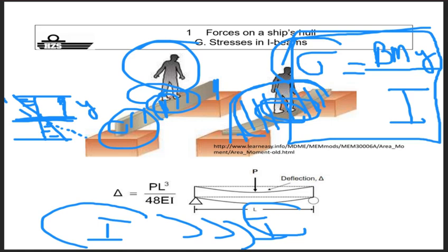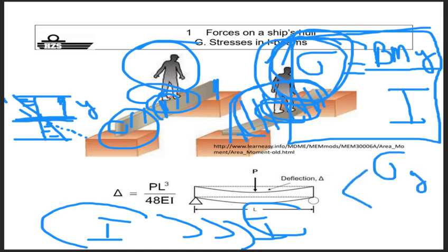That is the idea behind shear force and bending moments. We have restrictions, and this stress, in order not to fail, should be lower than your yield stress, taking into account, yes or no, a safety factor or safety margin. And that's the whole idea behind it.